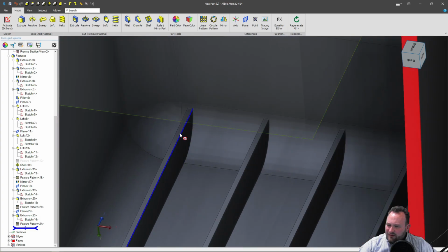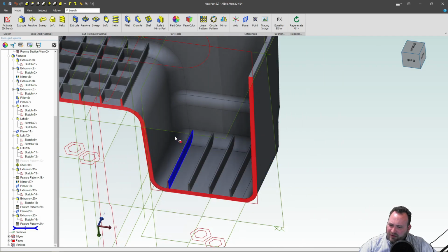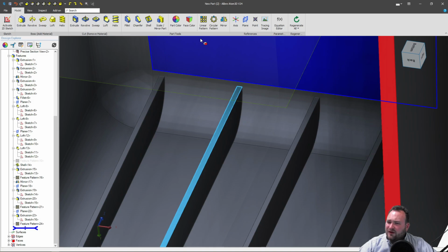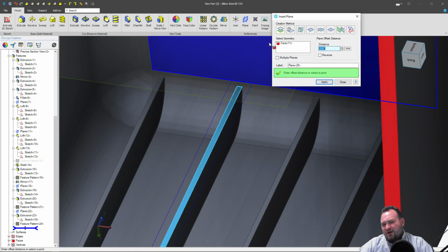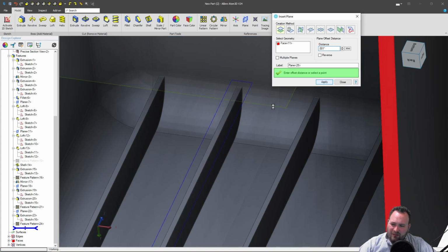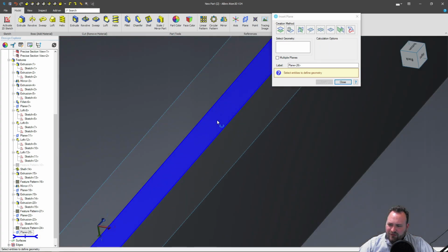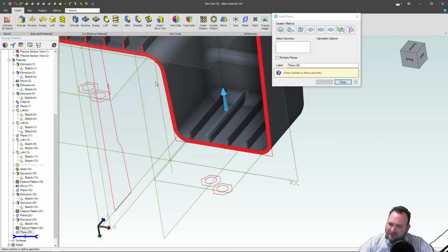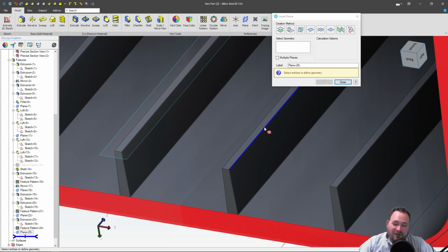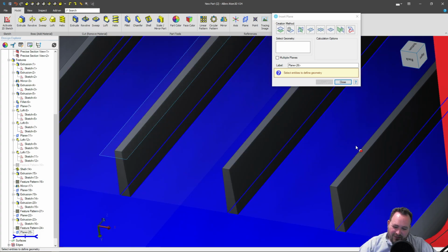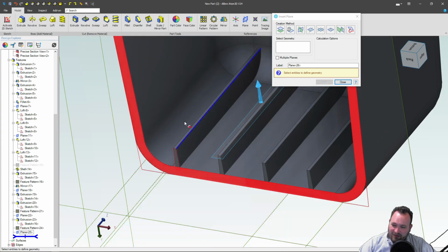And the next thing is, how do we deal with ribs crossing that isn't what we've just already done? So I'm going to grab this top face. We're going to go with a plane. We're going to say 0.001, right, 1 thou higher, and apply that. So with this difference, you can do little tricks, like the method that we did last time and just have one rib be a 10,000th of an inch higher than the other one, which is insignificant for tolerances, but which the CAD system can still pull up to next geometry.